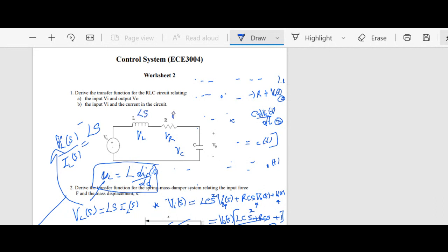For the resistor, it doesn't change. You can go through the same thing I did just now. For capacitance, it actually is 1 over CS. Again, you can do the same thing by writing the expression for the capacitor voltage and current. Let me actually write it, I'm a visual person. For the capacitor, IC of t is equal to C dVC/dt.